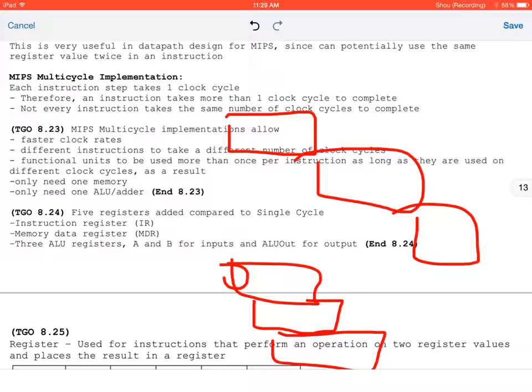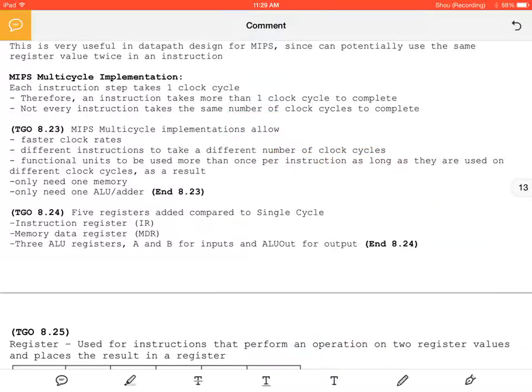But for example, in R-type instruction, this is a good example. We'll be going over this FSM later today. In R-type instruction, we'll start with you fetch the instruction like normal, then you decode the instruction like normal, then you're going to execute and get everything from the registers, put into the arithmetic logic unit, but you're not using the data memory, right? You're taking that value from the arithmetic logic unit, circumventing the data memory, and just storing it into the registers, right?